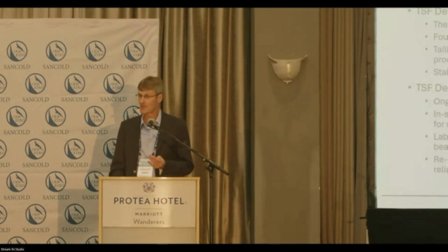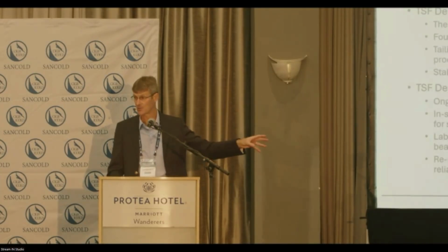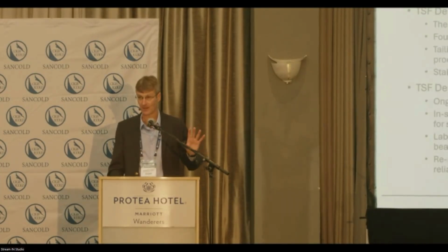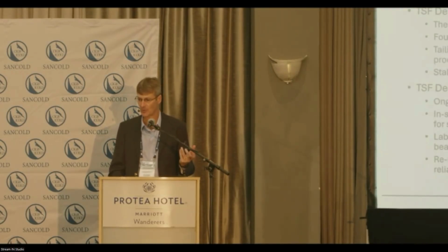If you haven't got reliable samples, what are you going to design to? We shouldn't be in that situation where a client is telling us, oh, just assume the tailings behaves like the mine next door. We used to do things like that. We can't do that anymore. We shouldn't be accepting that. We should be getting to a point of reliable information for design purposes.